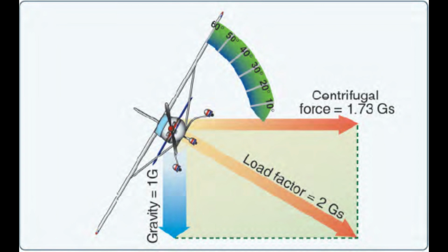While a course in aerodynamics is not a prerequisite for obtaining a pilot's license, the competent pilot should have a solid understanding of the forces that act on the aircraft, the advantageous use of these forces, and the operating limitations of the aircraft being flown. For example, a load factor of 3 means the total load on an aircraft structure is 3 times its weight. Since load factors are expressed in terms of Gs, a load factor of 3 may be spoken of as 3 Gs, or a load factor of 4 is 4 Gs.